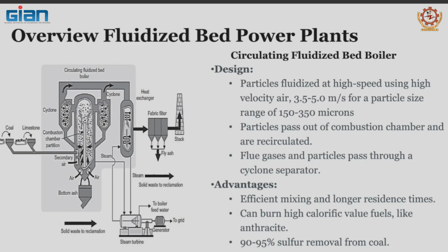As I said, at a given ratio, limestone particles are introduced. Now, the mixture is pushed in there pneumatically, and then you have your boiler here, and provide the primary air, and then secondary air, which we talked about, to provide the kind of complete combustion here.